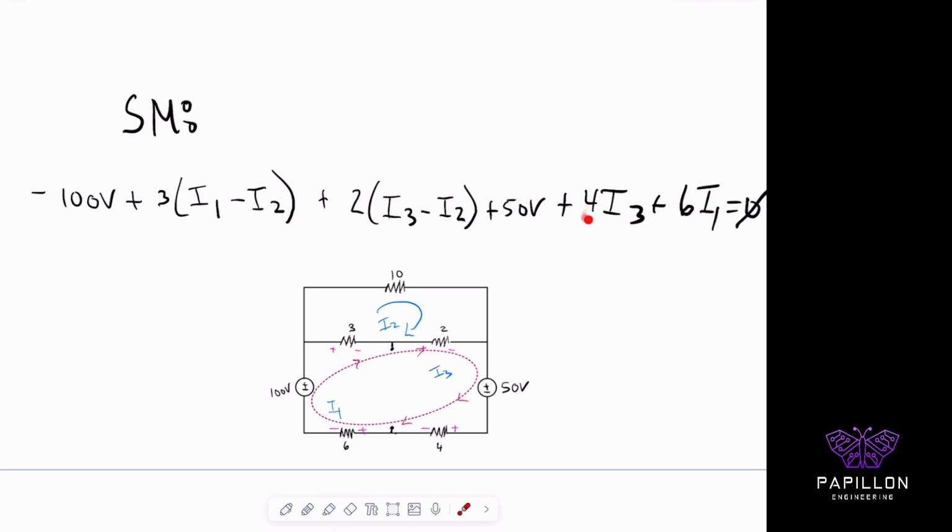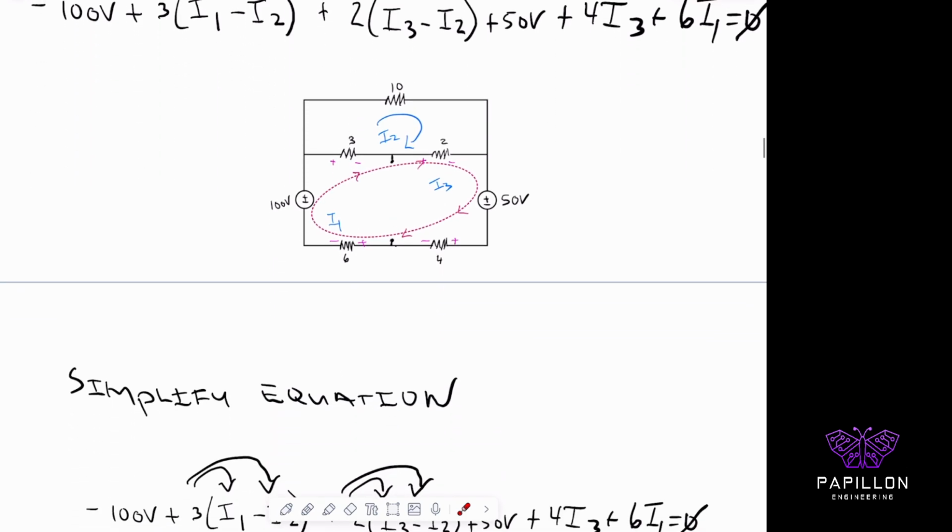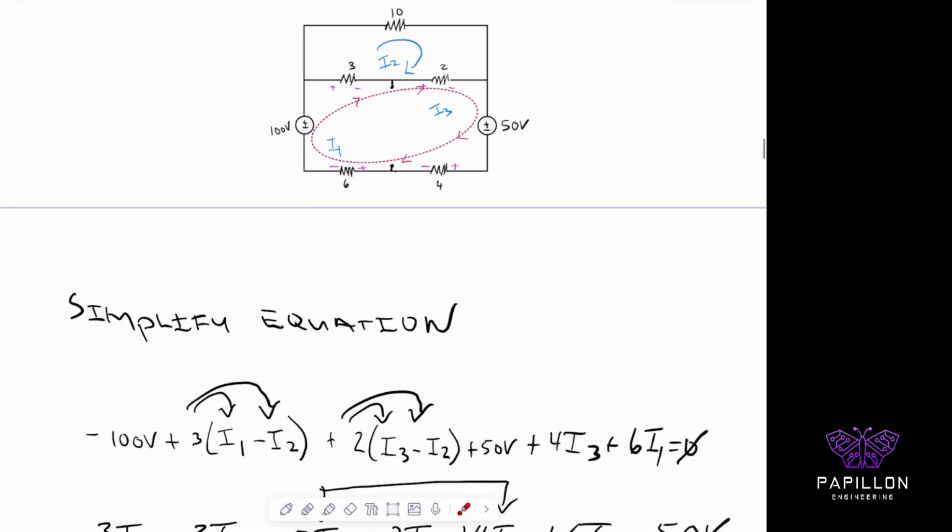See, these are all voltage sources. Take a moment to look at that. And again, we'll practice a similar problem in a few minutes so you can get a sense of how this all works. So what we're seeing is I wrote one equation that's called our super mesh equation. We're not done quite yet. We have one more loop, so I have to write that equation for that loop as well. And by the way, SM stands for super mesh.